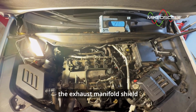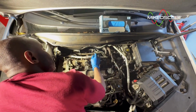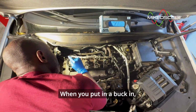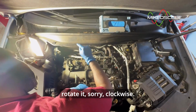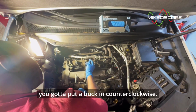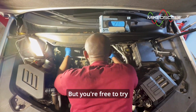Now the trick to putting the exhaust manifold shield is when you're taking it out, you got to take it out clockwise. When putting it back in, you got to do it counterclockwise. Okay, so taking it out, you got to rotate it clockwise, and then putting it back in, you got to put it back in counterclockwise. So that's what GM says. And I tried it, it works. But you're free to try it too if you want.